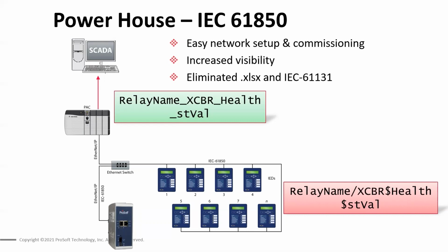And with our standalone gateway, we have this configuration software, which allows you to map data, and then it builds custom add-on instructions that can be used in RSLogix 5000 or Studio 5000 to give you that exact same tag name all the way up through.